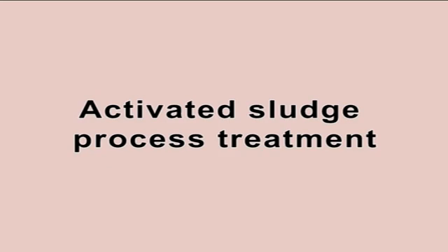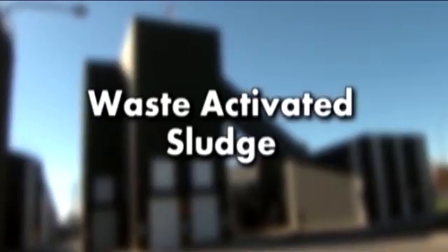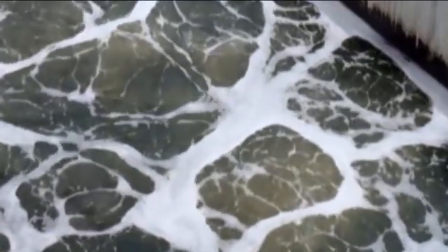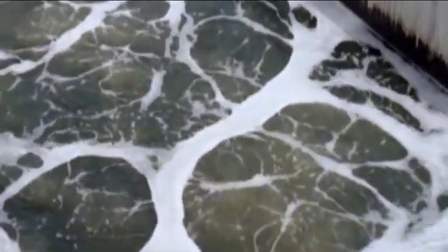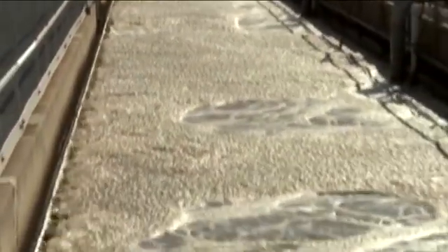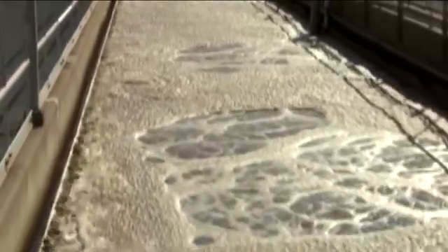In an activated sludge treatment system, an acclimatized, mixed biological growth of microorganisms is brought into contact with organic material in the wastewater in the presence of excess dissolved oxygen and nutrients such as nitrogen and phosphorus. The microorganisms convert the soluble organic compounds to carbon dioxide and cellular material, that is new biomass. Oxygen is obtained from applied air, which also maintains adequate mixing. The bioreactor effluent is settled to separate biological sludge, and a portion of the sludge is recycled. The excess is sent for further treatment such as dewatering.